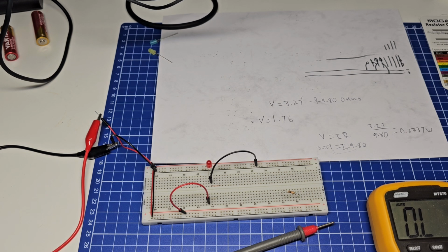And we learned that an LED can't be measured directly, can't measure its resistance directly. You have to measure the voltage drop. So I think next time we can do a quick LED thing. I will set up beforehand a string of LEDs, make sure they turn on and that I have the resistor set up correctly, and we can see what the voltage drop is from there.